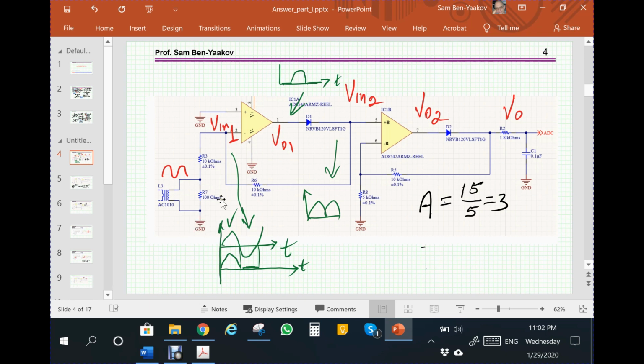And in this case, this positive voltage now goes from here to here to here and to here. So we now are getting here the positive voltage itself. This is here the inverted negative voltage. So here we have a rectified voltage.